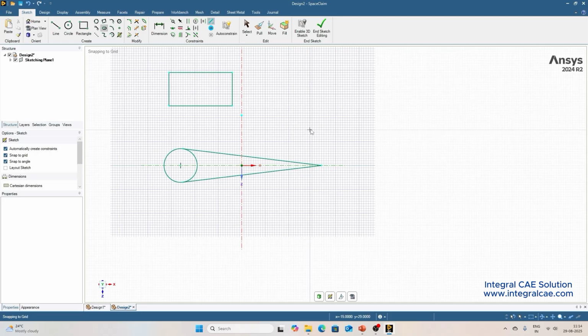In the grid, where we click becomes the center of the ellipse. And you will notice a line has started on both sides of the center. This is actually the first diameter. You can change or set this first diameter value if you want and click once to fix this first diameter. Let's fix this first diameter, let's say at 34 millimeter, and left click.